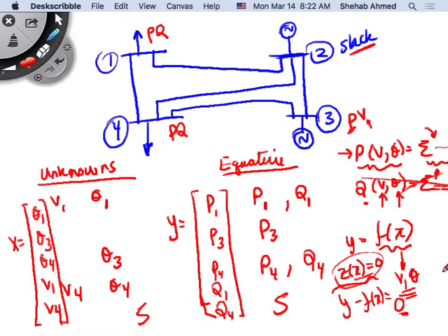So we will have to agree on a convergence criteria. Convergence criteria is something you control. Like in PowerWorld, you control the convergence criteria to be maybe 10 to the minus 5, for example. It's never going to be 0. It's going to have to be smaller than a certain value. Nobody can guess the perfect value. These things will not converge to 0. They will converge to something small, because the system is always changing. So you will agree on some convergence criteria.